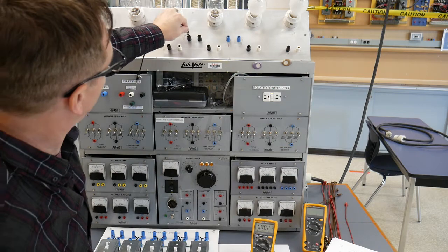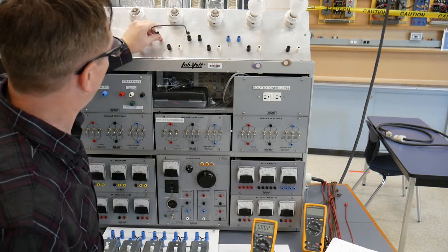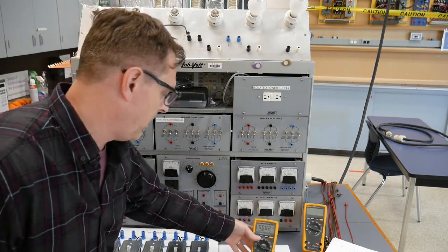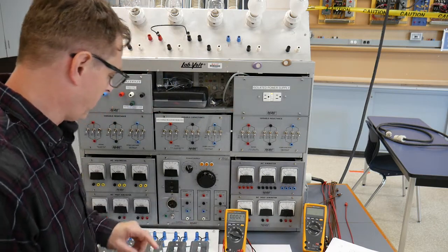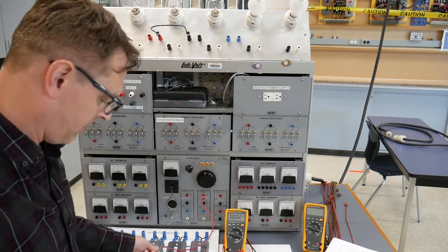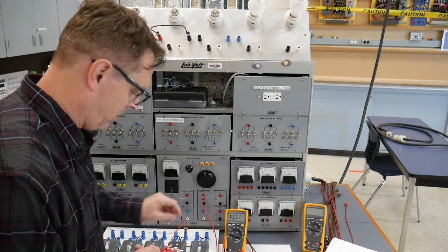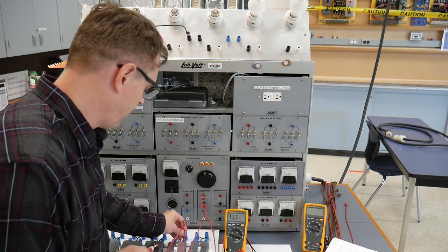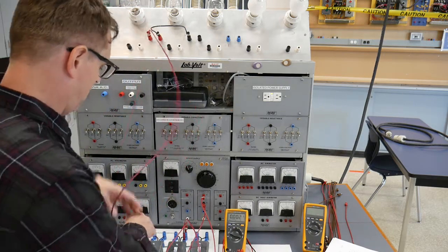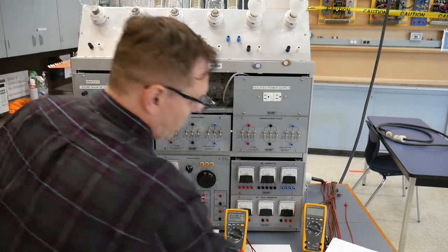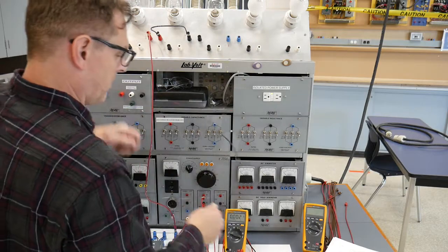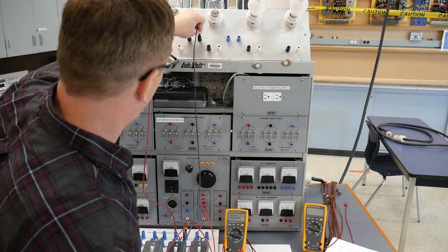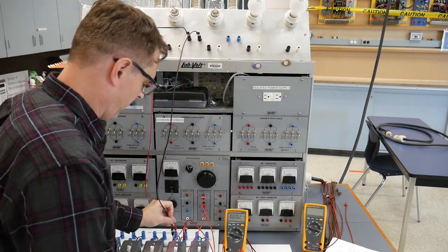We're just going to go in between. That's not a very good, yeah, that's okay. In between there and there. Now this is my double pole single throw and it's going crisscross. So we know we need an input coming from this side, heading to 1, and an input from another line conductor heading to the other, and then we're going to go up to that, and we need one more jumper. That's going to be too short. Grab a longer one from this side going to the other side of the switch.